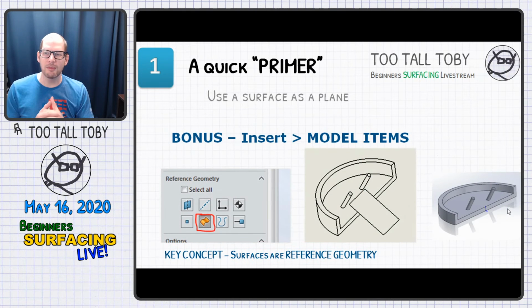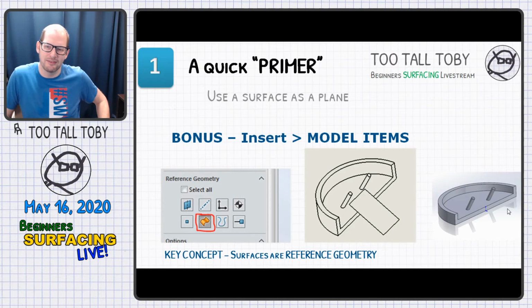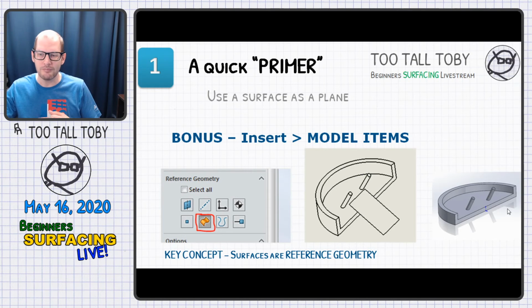You can also see here that we talked about a little bit of a bonus tip. And we also discussed a key concept. Surfaces are reference geometry. They're theoretic in nature. They have no mass, they have no volume. They should be treated in your mind kind of like planes and axes. They're used to help construct the model, just like we use the surface here to help construct the model. But you're not using the surface as your final handoff to the next stage of manufacturing. And we talked about a little bonus tip. You can go into the command Insert Model Items, and that'll let you bring those surfaces into a drawing.